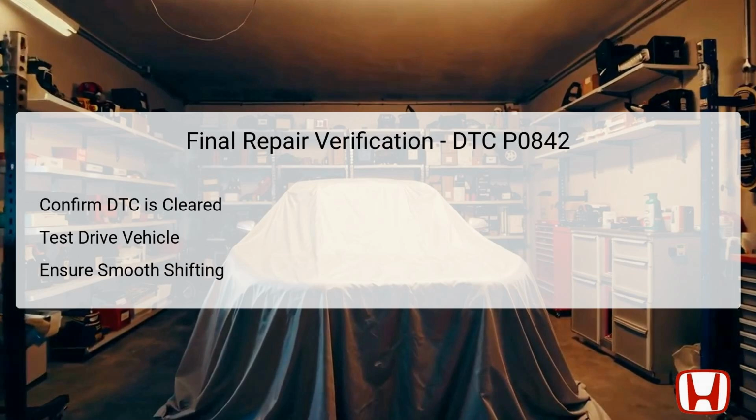During the test drive, observe the transmission for any signs of erratic behavior or issues with shifting between gears. The goal is to ensure that shifting occurs smoothly, without hesitation or confusion from the transmission control system. Successful verification concludes the repair process, confirming the electrical issue has been resolved and the transmission is functioning correctly.